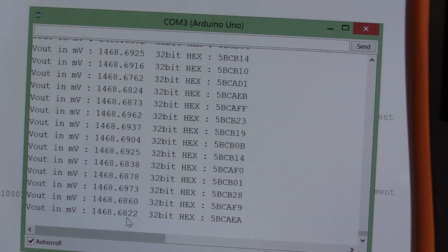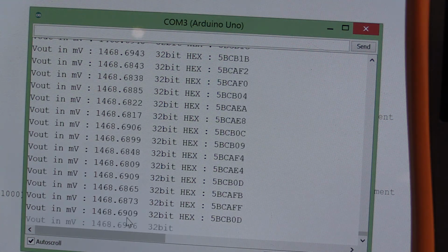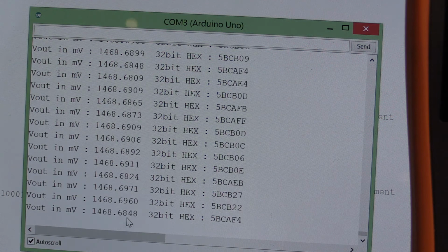And I think that I happen to have these 24-bit ADC. What I will do in another video is maybe try some other ones. I do have some 16-bit ones, and we'll see if they are as stable as this. So one of the reasons I'm suggesting that is because even though you go to 16-bit, there are still issues with effective bits versus actual bits.